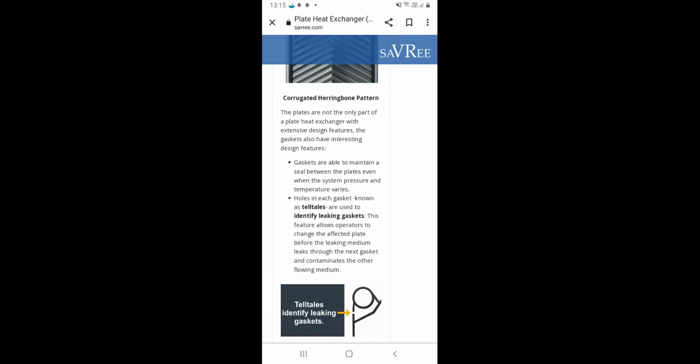You can change the brass tube also, if an onboard spare tube is available, and then you can replace the tube. But if it is not feasible and you don't have a tube, then at that time you have to put in a plug.